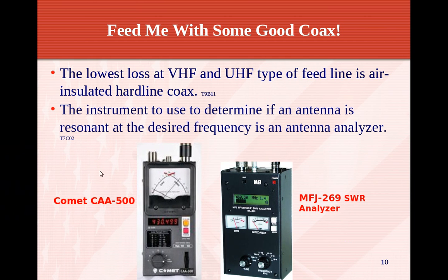So these are a couple of different antenna analyzers that are out on the market. These work very well. They're very small actually. They look bigger here, but they're about the size of 2 cigarette packs if you stack them side by side. And they'll measure your SWR, your impedance, anything like that. So these are pretty useful, handy tool.